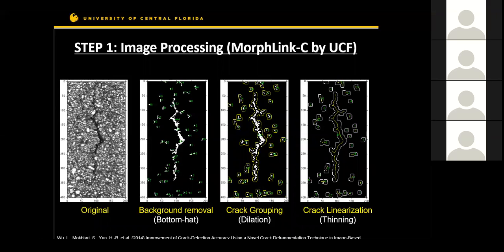Most image processing techniques have this limitation that when you do the detection, the results come out fragmented. On the first image, the original image, we see one crack. But on the second image from the left, we see multiple detections. So it is detected in fragments. That's the problem of fragmentation. Many methods have been proposed in this paper.